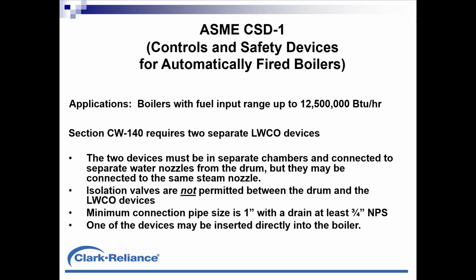They require two separate devices in separate chambers. They require that each device be fed from a separate water pipe coming off the drum. However, they can share the same steam pipe coming off the drum. The reason for this is if one water leg becomes contaminated with sediment buildup, it does not affect both devices.